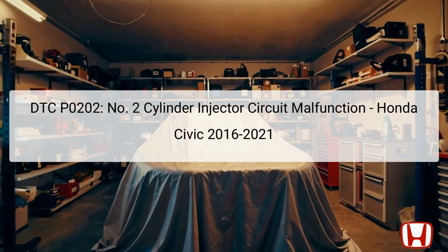The DTC P0202 indicates a malfunction in the number 2 cylinder injector circuit, which is critical for the fuel injection system in Honda Civics from 2016 to 2021. The primary function of the fuel injector is to introduce atomized fuel into the combustion chamber, facilitating optimal engine performance and efficiency. The number 2 cylinder injector location is on the engine, where it directly connects to the engine's fuel rail. A failure in this circuit can lead to incomplete combustion, misfiring, or a failure to start the engine.